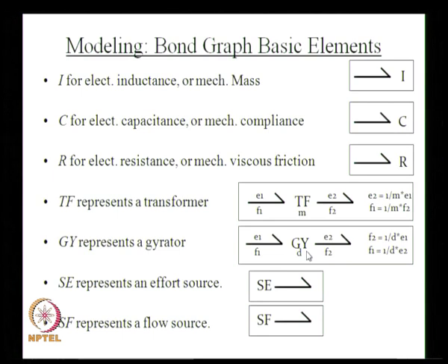For example, if you have an electric motor, we give a current and you get a torque output. So the flow parameter is converted to the torque parameter. Here is a conversion from flow to effort. That kind of relationship is represented using a gyrator element.